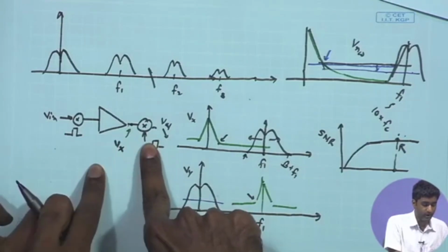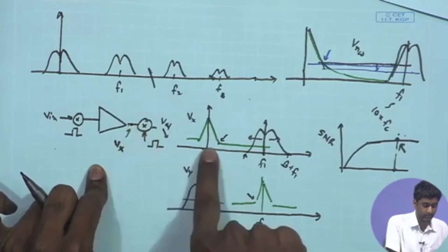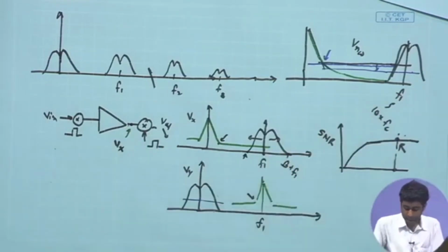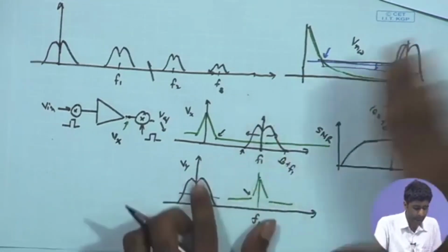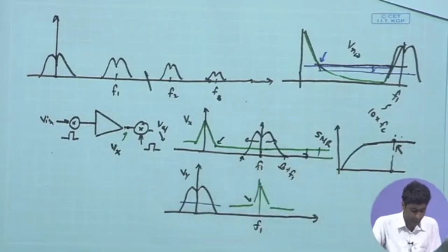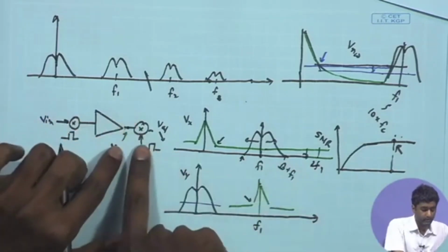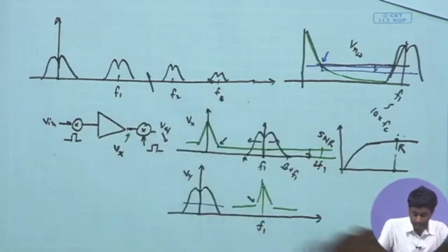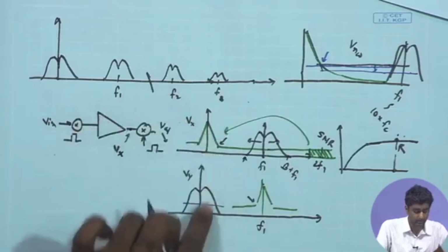So, you have not only f1, but the higher harmonics of f1 multiplying this 1/f noise spectrum. Therefore, this white noise that was present at all the higher frequencies, because it is continuous, is going to be present at even higher frequencies. So, it is also going to have spectrum close to say 2 f1 and 3 f1 and so on. And now, when you are multiplying this 2 f1 component with this f1, definitely the white noise component in this interval is also going to get shifted back and come to this level.